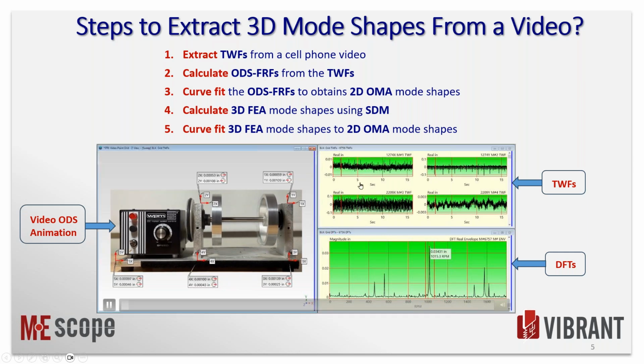So you can't see it as much in the time waveform, but if I go to the frequency waveform, you can actually see the mode shapes of these rotors, and there's no way you could instrument it. Yeah, with a laser system, but now you're talking hundreds of thousands of dollars. Here you can actually see the modes of the rotors. This one's very clear. This is a mode shape dominated mainly by the unbalance of this pulley here, but you're getting information you couldn't get any other way.